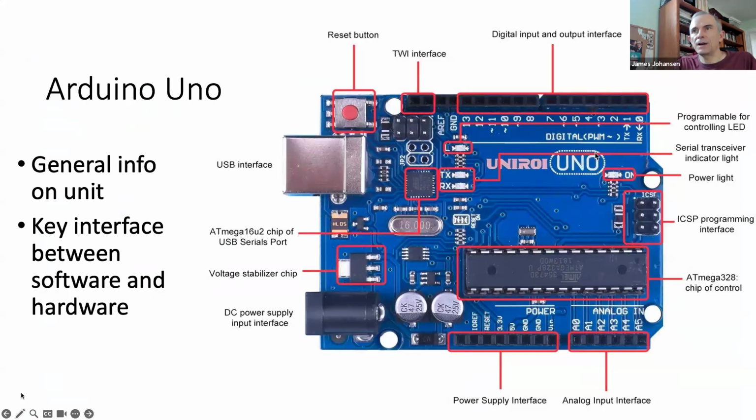This is a blow up of the actual Arduino Uno. There are some interesting things on here. Instead of having a CPU, it has what's called a microcontroller. This is the workhorse microcontroller for managing the inputs and outputs. Then there's another microcontroller for the interface with your computer. This is an I/O card that speaks USB, and this is how you're communicating directly with your computer.